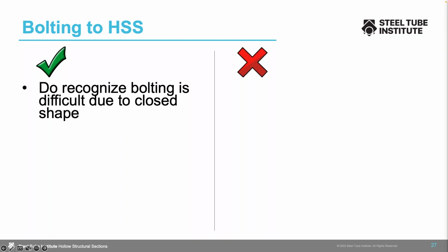If you definitely need to do it, then don't forget your access holes, because unless you're at the end of a section, there would be no way to get your tool in there to tighten the nut on your bolt.